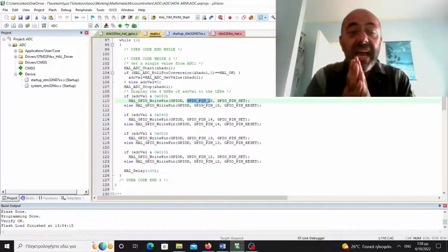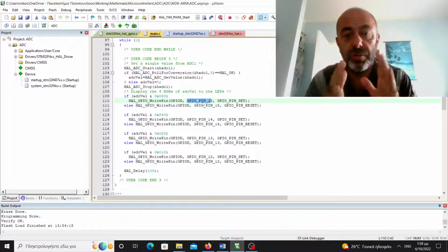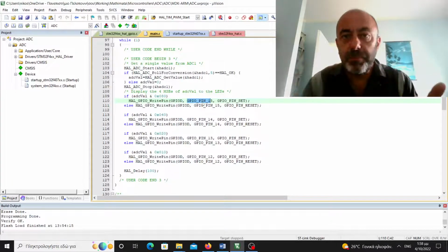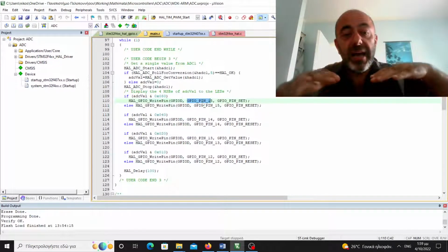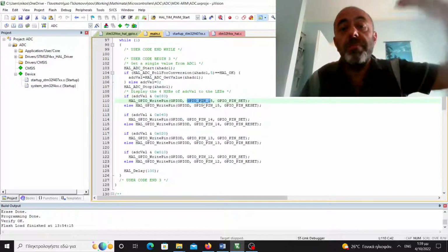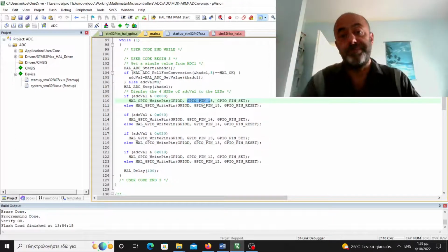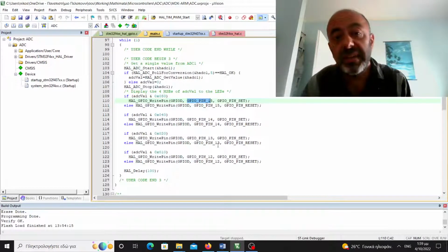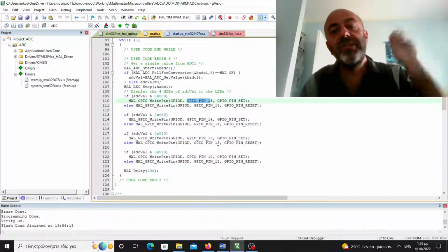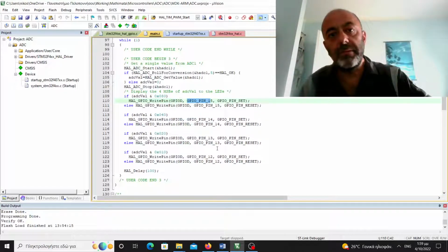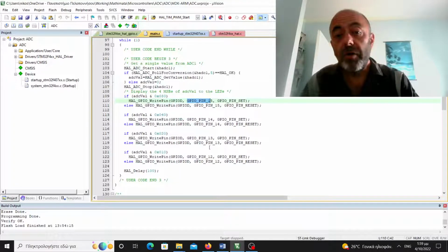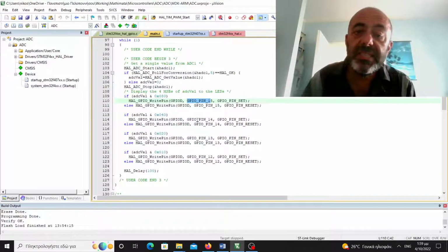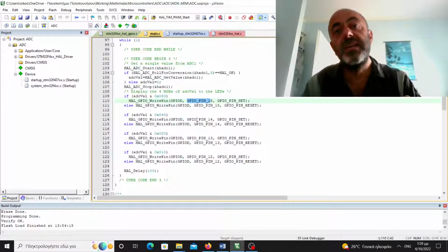So, when I had connected my 3 volts to the analog digital converter input, this means that I had a large value where all the most significant bits were all 1. So in this case, all the LEDs were turned on, as you saw earlier. When I removed the connection and the input of the analog digital converter was 0, then none of the most significant bits was 1, so none of the 4 LEDs had been turned on, so all my LEDs turned off.